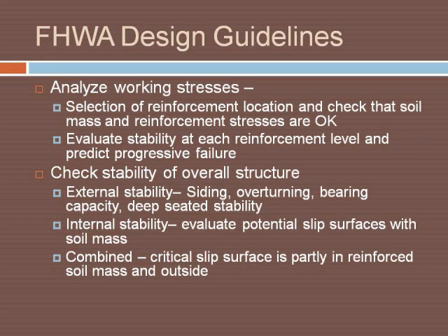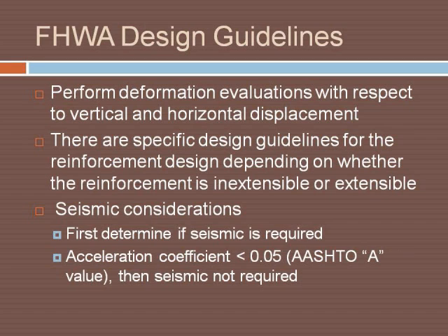Included in that is checking reinforcement location and stresses in the soil and the reinforcement, and overall stability of the structure: external stability, internal stability, and combined stability. Note that there are specific guidelines for reinforcement using inextensible reinforcement or extensible reinforcement.